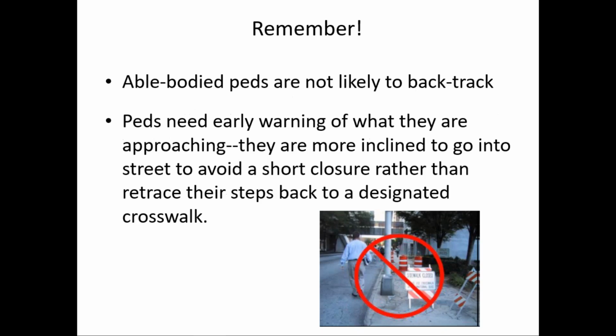And remember, able-bodied pedestrians are not likely to backtrack. Like this fellow you see here, sidewalk is closed. That's not a proper closure from a PROWAG perspective or MUTCD perspective, but notice he probably had no intention of backtracking. He's going to walk in the street.